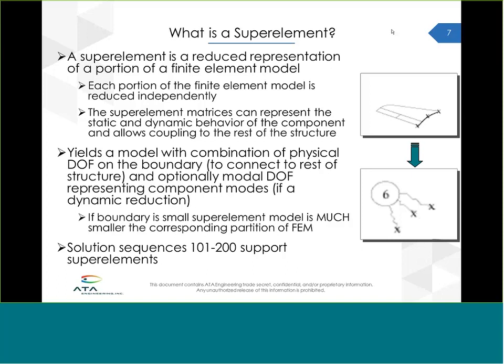Superelements are supported in Nastran solution sequences 100 to 200. So there's a very wide range there: statics, buckling, dynamics, even nonlinear analysis, transients, both time domain transient dynamic analysis, as well as frequency response dynamic analysis. So there's a lot of different applications for superelements.